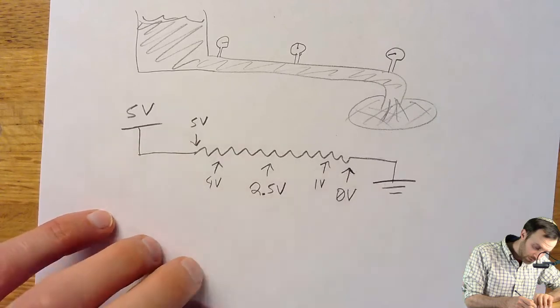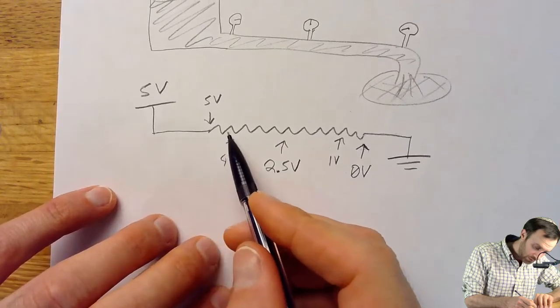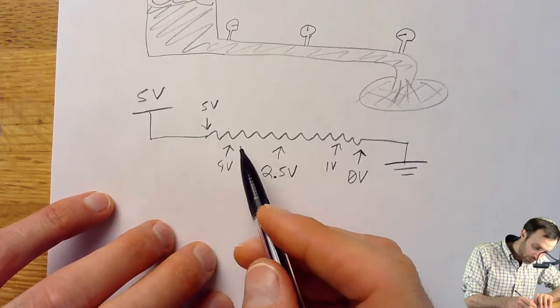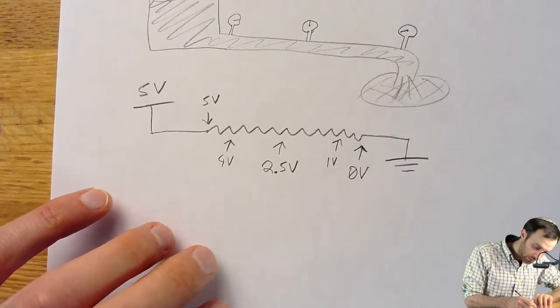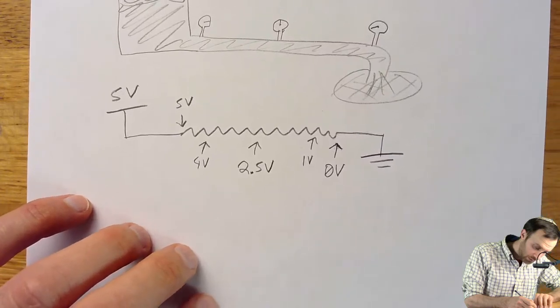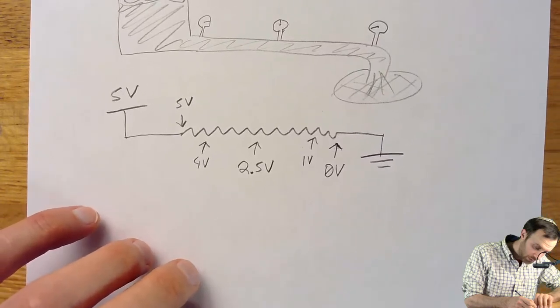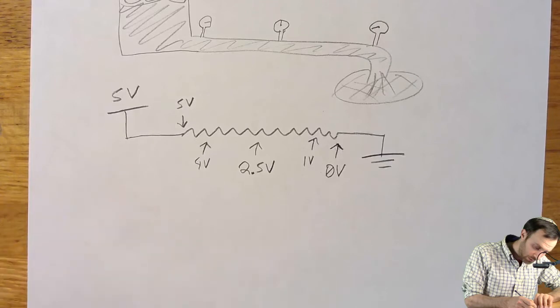So who cares? I'm going to show you we care. We're going to take advantage of the fact that the voltage falls across the resistor. We're going to take advantage of that to build a device which acts as an input. The Arduino, after all, is a voltmeter. It can measure voltages. It can't do a whole lot else. It can provide voltages. That's what we've been doing so far. We've been providing 5 volts to an LED or not providing 5 volts. That is a blink, either providing or not. Goes on or off.